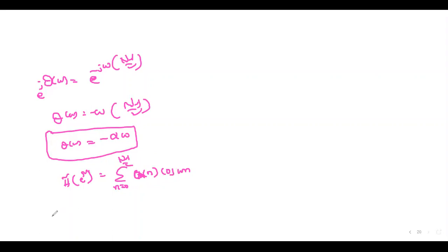But what we want is the magnitude response of the linear phase FIR filter. Even though it does not have any complex quantity, it still varies between plus and minus because of the cos, because cos value varies from minus 1 to plus 1. Therefore, we need to take the mod of this. That is the magnitude response.